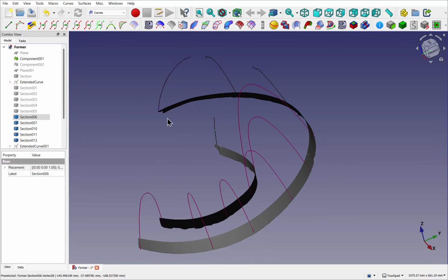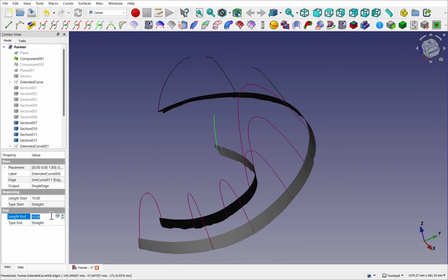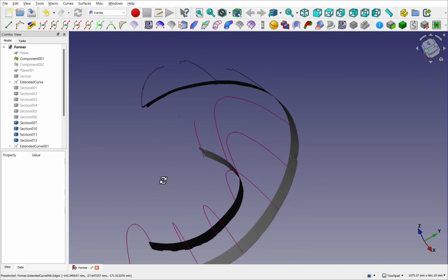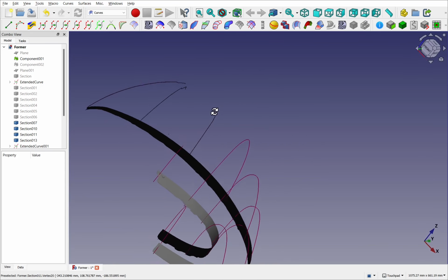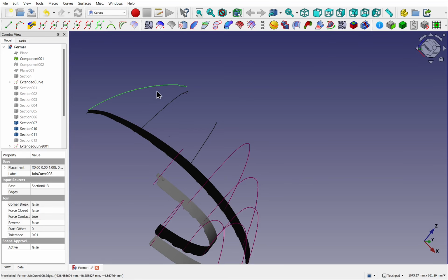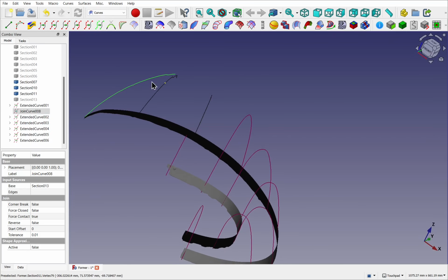Let's do this one first. And that one's a join curve, and I select the join curve, curve extend, and I select it first. So this one needs to go 35. It should be the end. Click off. There we go. That's in. We need to edit this one. This one looks fine. Something behind there. What's that behind there? Press the space bar. We've got a join curve in there, which we can use. So I'm going to extend that join curve.